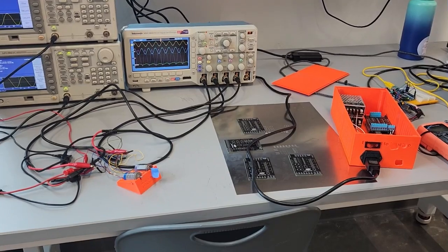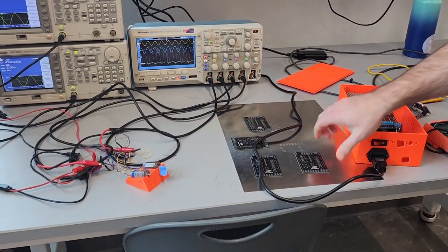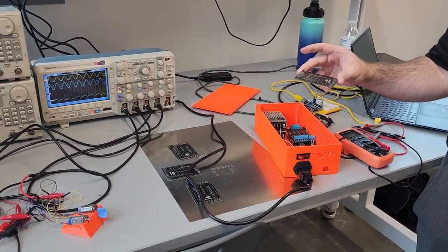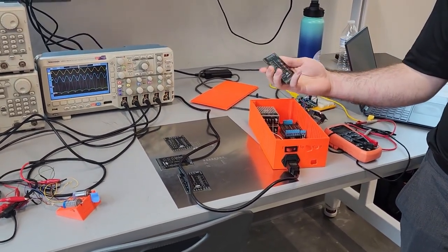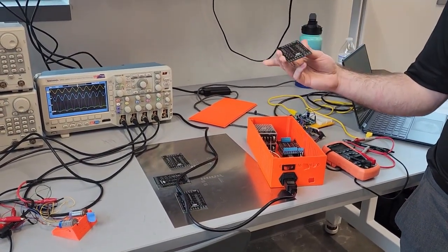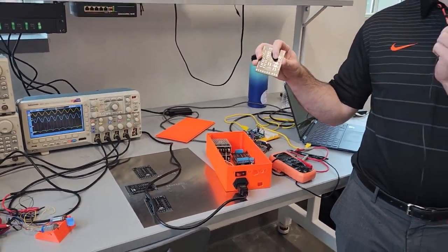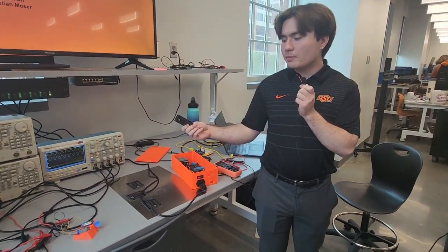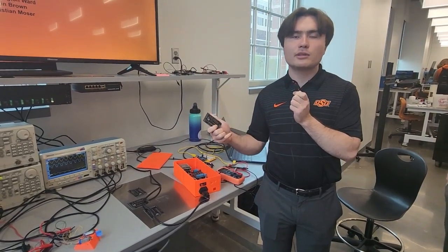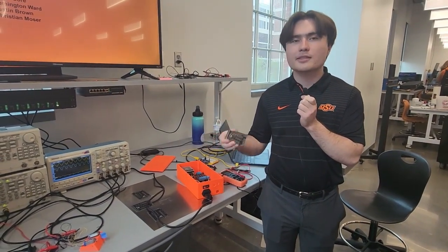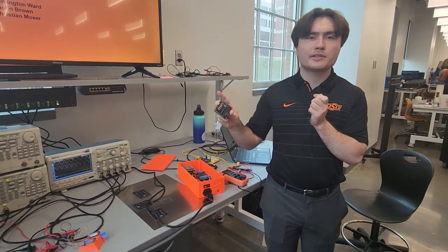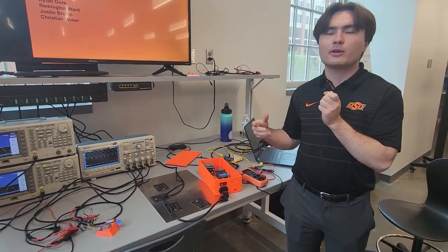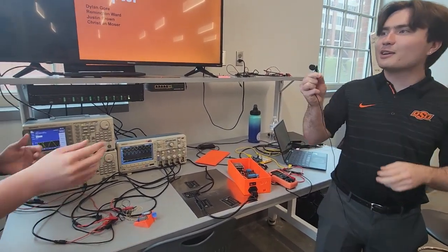So you want to go next? Talk about the PCBs? Okay, yeah. After we picked out all the components we wanted to use, we put it all onto KiCad, which is a PCB designing software, made a schematic, and then we laid out and routed each trace on this board, sent it off to get it printed, and then we put all the components onto it with solder paste and used a reflow oven to bond them all to this PCB. And it all fits onto an Arduino Uno, which is our microcontroller for this project.